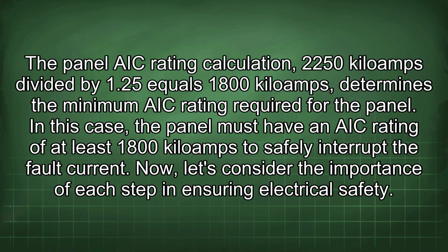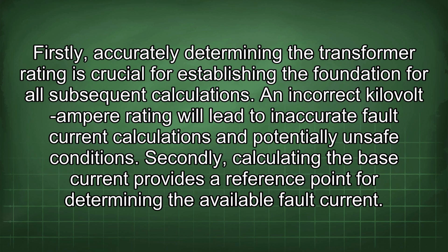Now, let's consider the importance of each step in ensuring electrical safety. Firstly, accurately determining the transformer rating is crucial for establishing the foundation for all subsequent calculations. An incorrect kilovolt ampere rating will lead to inaccurate fault current calculations and potentially unsafe conditions.